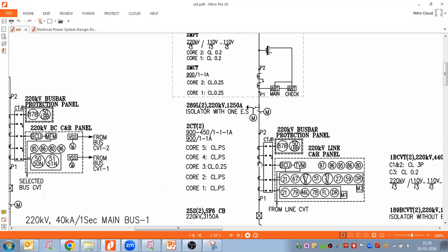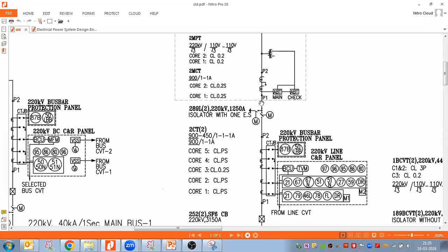If the CT is over here, then the CT will sense the fault only when the current reaches this CT equipment. But if the fault is passing through three equipment, those equipment first face the fault current. I need at least one engineer to attest so that they can respond whether they are getting my point or not.